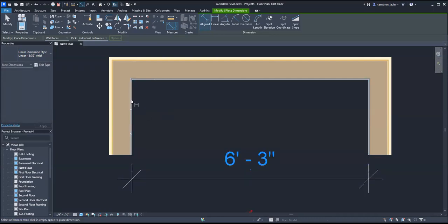If I tell my construction guy, hey, I want a wall that is 6 feet 3 inches from drywall to drywall, that means that the framer, the person who's doing all of the wood framing, is now going to have to take that dimension and do the math in their head, which is, okay, now I have to do 6 feet 3 minus 5/8 drywall on this side, 5/8 drywall on the other side. That is 1 1/4. So 6'3" minus 1 1/4, that's 6'1 3/4, right? You see how that math happens and it takes people a while. And when you're on a job site, you're moving quickly.